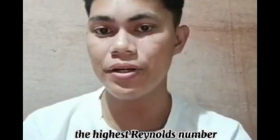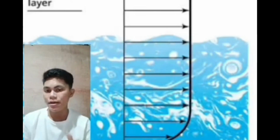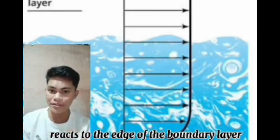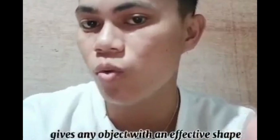At a higher Reynolds number, the boundary layer is turbulent and it is characterized by being unsteady, or changing with time, meaning swirling flows inside the boundary layer. The external flow reacts to the edge of the boundary layer just as it would to the physical surface of an object. So, the boundary layer gives any object an effective shape, which is slightly different from the physical shape.